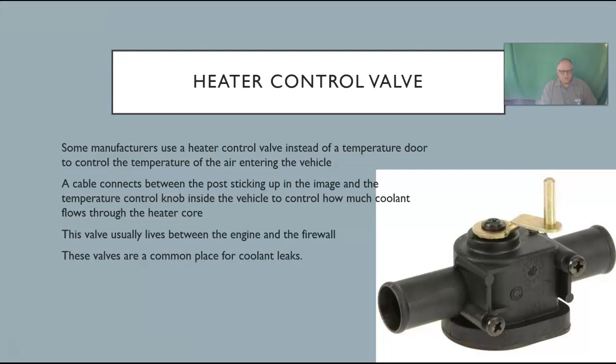So when a vehicle gets about 10 years old or so, keep an eye on this piece. If you see coolant on this and not anywhere else, it's starting to leak, you're going to tell the customer they need to replace that valve, because once they begin to leak, they'll fail much quicker. And that small little leak that starts off becomes a pretty big leak fairly quick.